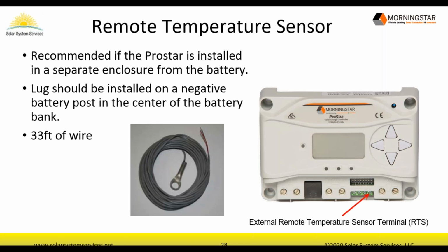Okay, I mentioned the remote temperature sensor before. It simply connects to the terminals there, as shown on the screen, and it's just 2 wires. It is not polarity sensitive, by the way, so it doesn't really matter how you do it. The standard cable is 33 feet, which should be enough to get you to wherever the battery is. And there is a lug on the end of it.